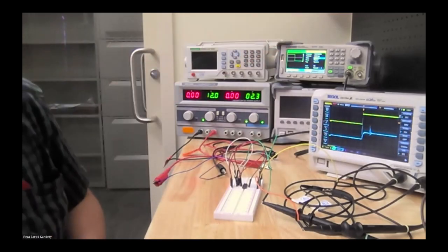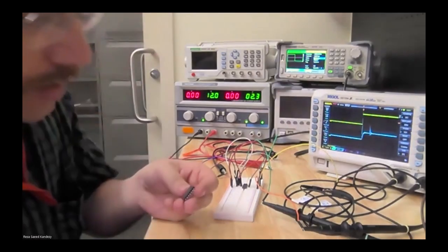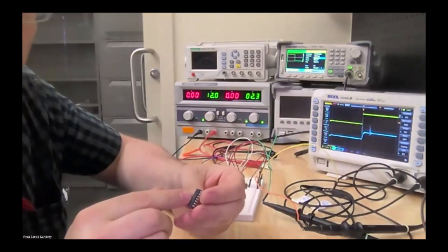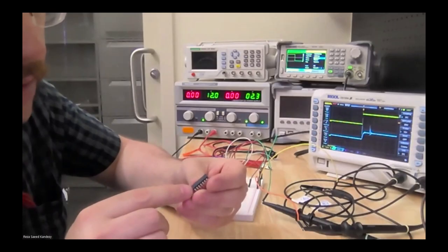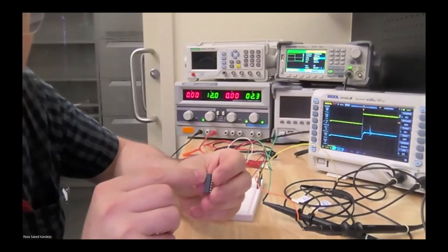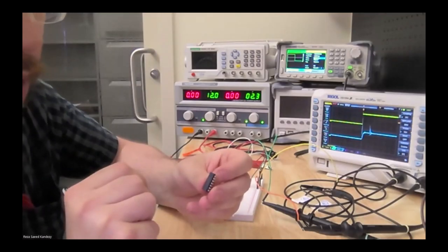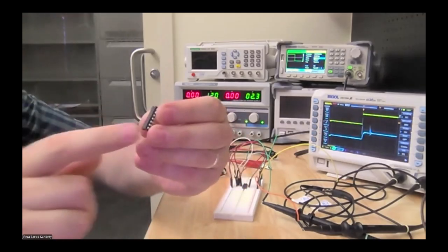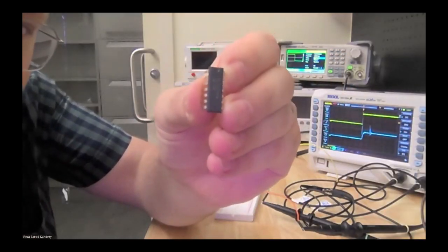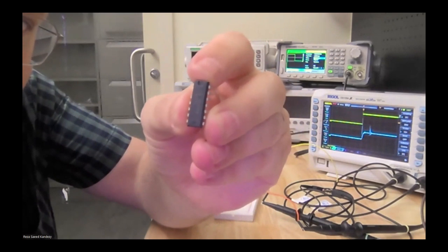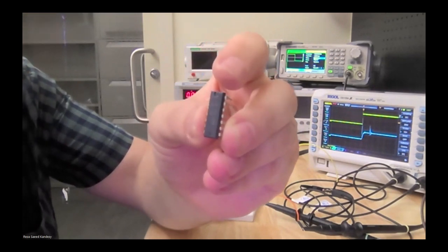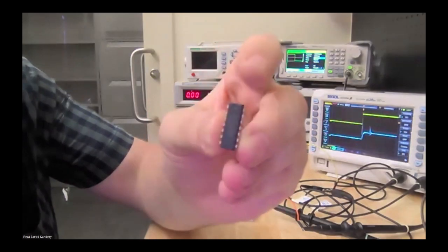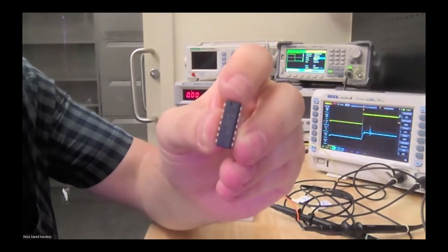And then we use the measurement. Now, before I talk about this measurement, I chose another type of LM324. The reason is that some of them don't have that dot at the edge that we talked about, so you can't basically follow the previous one. Now, on this model, as you can see, there is another aspect. If you can detect this dip in the surface of the op amp, this is another indicator to identify the pins.